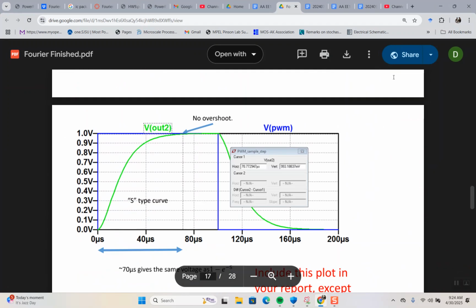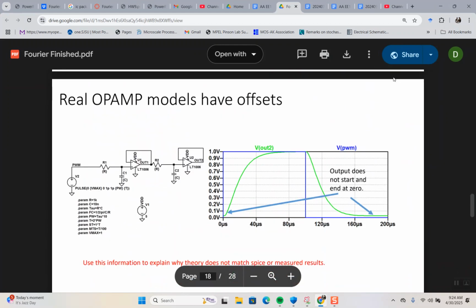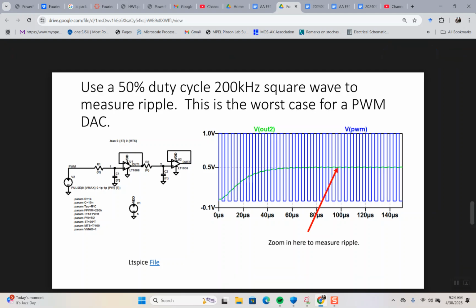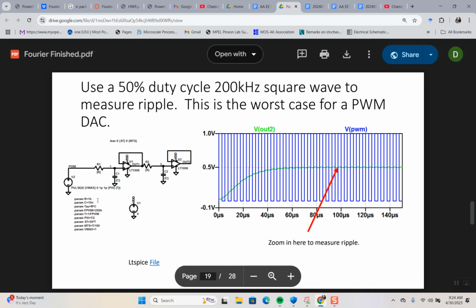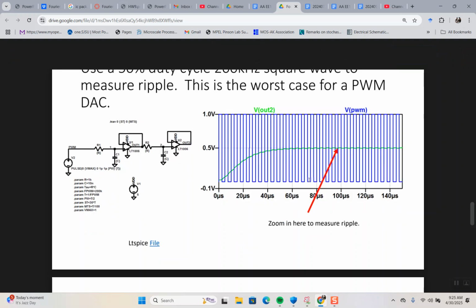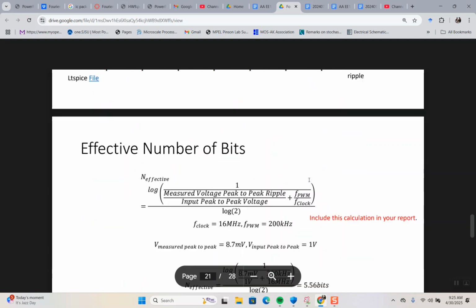And you can just see this. I'm just going through the step response of the filters, and then now I increase the clock frequency, and notice it's wiggling up and going to 50%, and you can see the ripple. Now this is a second order filter, so there isn't a 5 tau, but you can see that it looks like the step response of a second order filter. And that's zoomed in, so it's not quite a triangle, right?